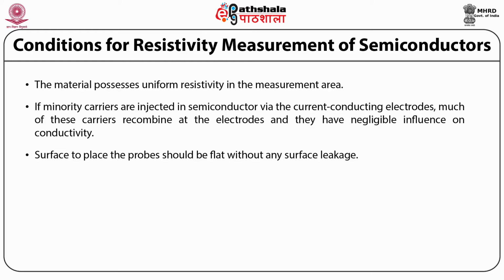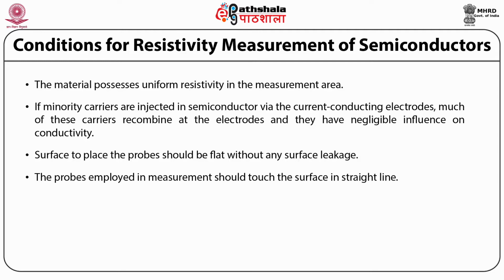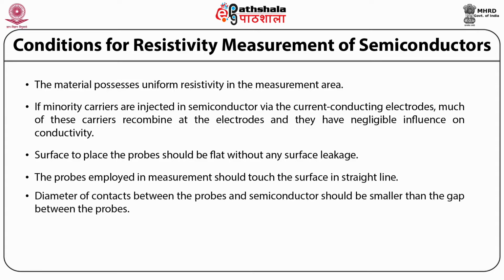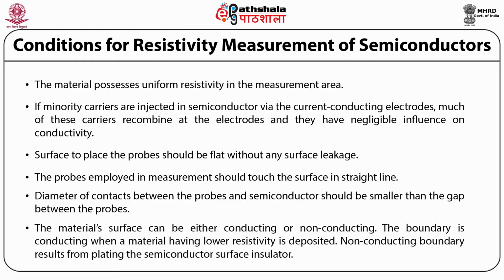Third, the surface should be flat without any surface leakage. Fourth, the probes employed in measurement should touch the surface in a straight line. Fifth, the diameter of contacts between the probes and semiconductor should be smaller than the gap between the probes. Finally, the material surface can be either conducting or non-conducting. The boundary is conducting when a material having lower resistivity is deposited. Non-conducting boundary results from plating the semiconductor surface with an insulator.